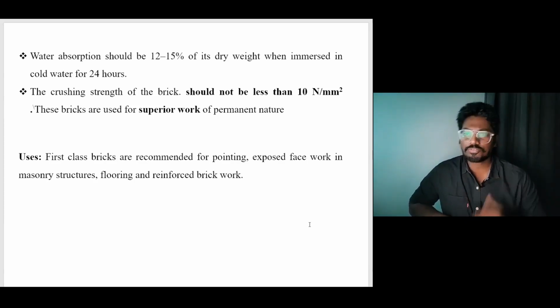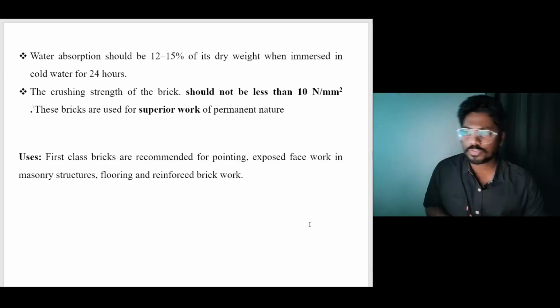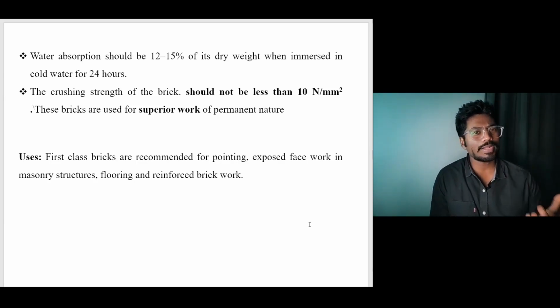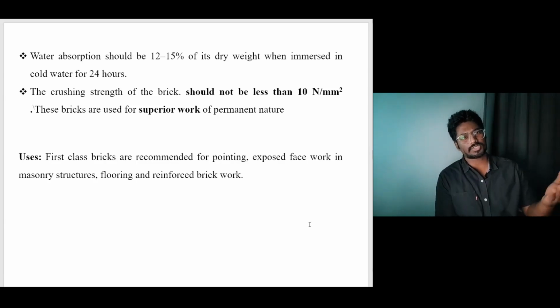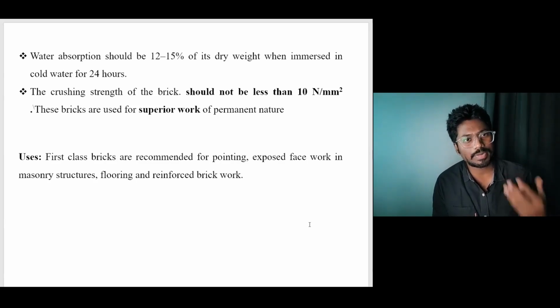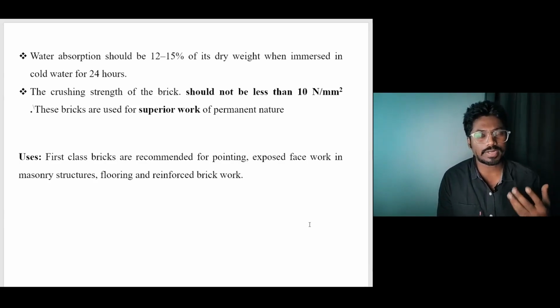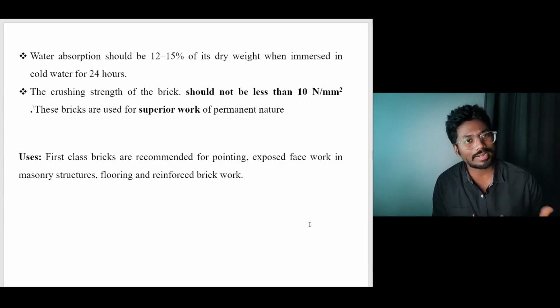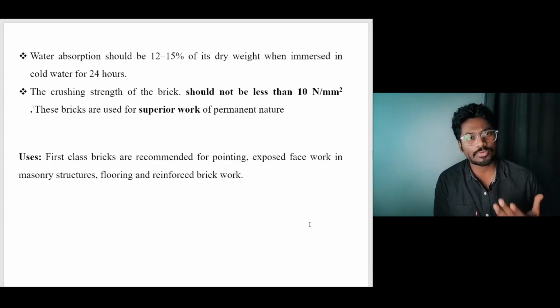Next, first class bricks are used for pointing, exposed face work, masonry structures, flooring, reinforced brickwork. All the load bearing masonry structures out there are made with first class brickwork. It has better resistance to load, better resistance to durability aspects, better resistance to any sort of wear and tear, and yes, it can be used for constructions that have more load involved in them.